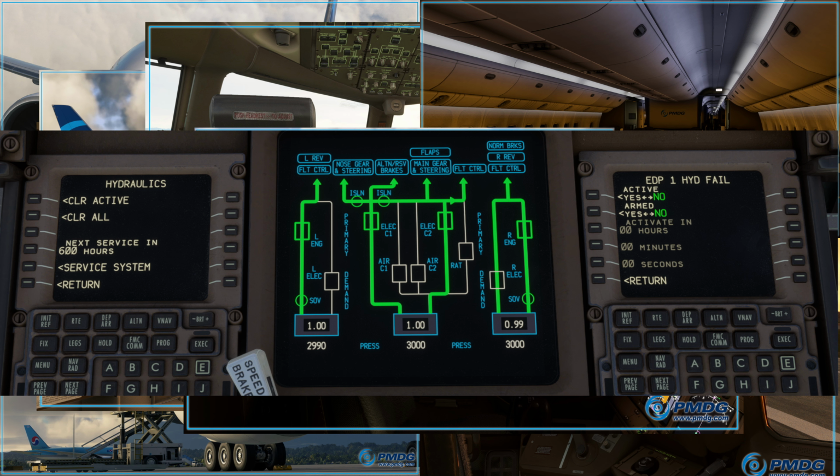It's really impressive what kind of protections are built into aircraft in case of system failures. For example, the engine anti-ice valves have a similar system that in case power is lost, they simply get stuck in the open position so that engine anti-icing is continually applied. Really, really cool stuff there.